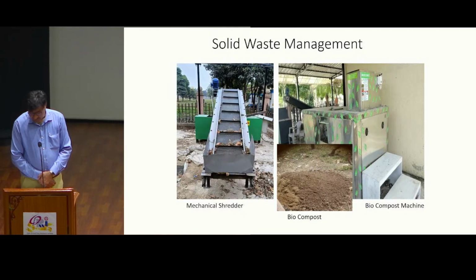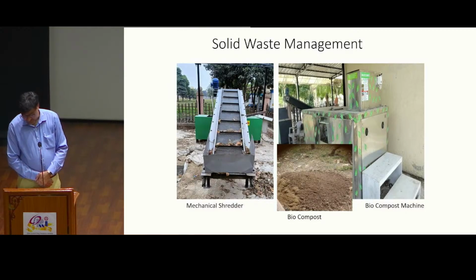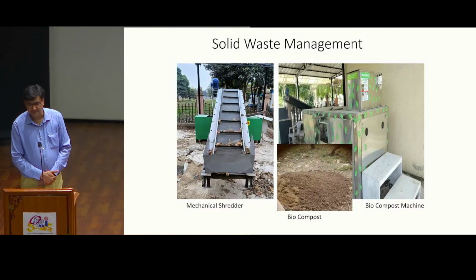The waste material first goes to size reduction units, followed by the digester through the hopper. The digester temperature we are keeping in the range of 60 to 70 degrees centigrade, with continuous mixing by an agitator rotating at 10 to 12 rotations per minute. The rate of aeration improves the digestion and removes odor generation during decomposition. The decomposed product with proper aeration is free from moisture and odor, with more than 80% volume reduction. From 500 kg we are getting around 100 kg of product.